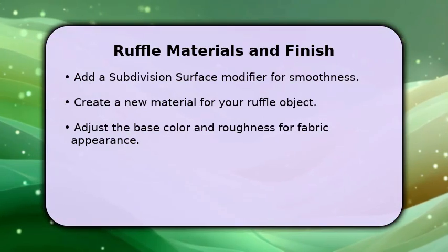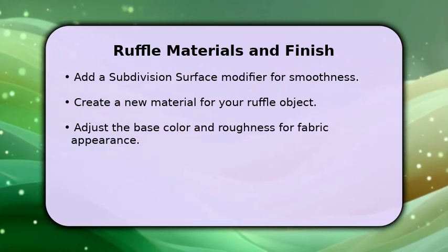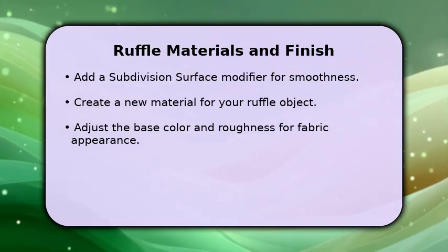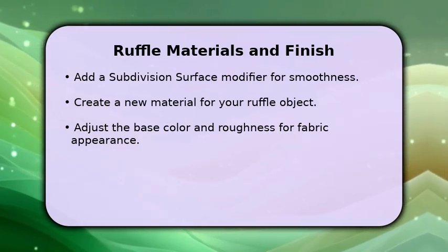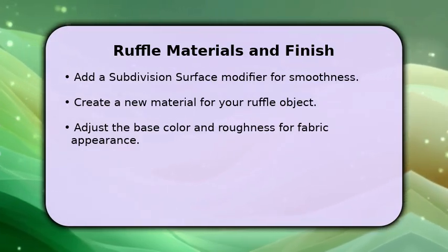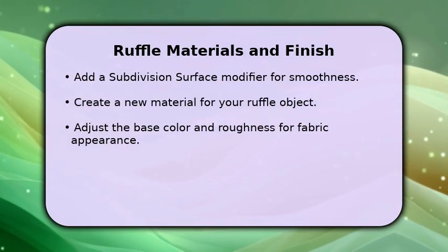To give your ruffles a polished look, let's work on the final presentation. Add a subdivision surface modifier, setting it to 2 or 3 levels to smooth out any remaining jagged edges. Next, create a new material for your ruffle.